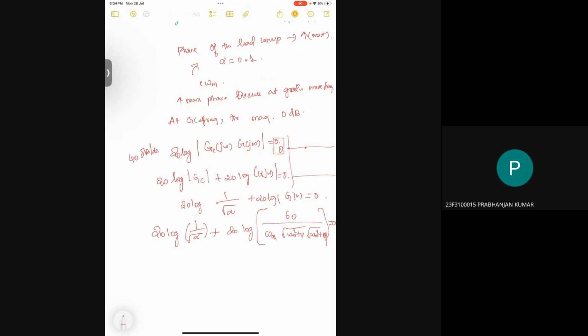Okay. So we are considering GC here as the lead compensator. When writing the frequencies and the gains for the lead compensator, we are using its parameter alpha. For G, we know the actual transfer function they have given here. Can you write the actual function for GC? I mean, what will be the expression for that, and where is alpha, so that we can understand?